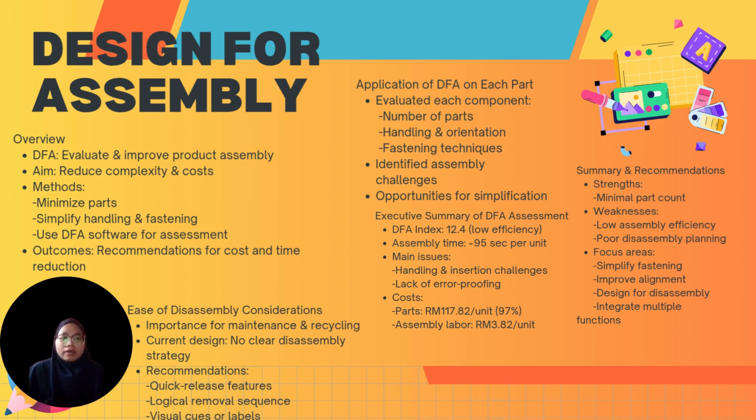We use DFA software to analyze the part, assembly time, and production cost to identify opportunities for improvement. In our assessment, we review each component's impact on assembly. We found that while the total number of parts is minimized, there were still challenges with handling, orientation, and fastening that increase assembly time and complexity.